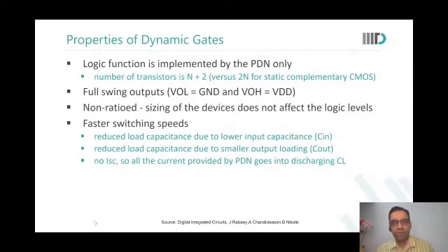Why 1/3? Just correct me. Sir, there are two NMOSes in stack. How would you size the NMOSes? 2 for the input and 2 for the clock. Two for the device, 2 for the input gate, and 2 for the clock. So what is the total load that the input gate is seeing now? 2 units, 2 NMOS, right?